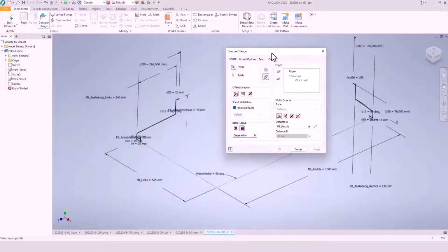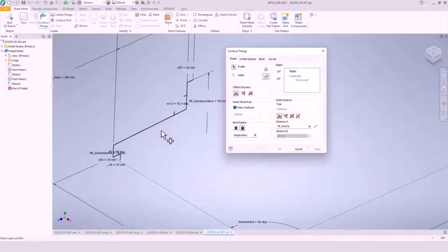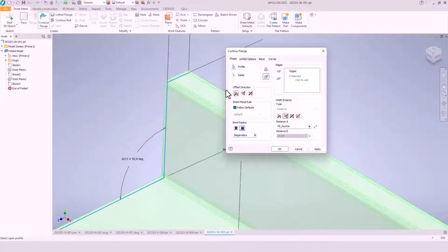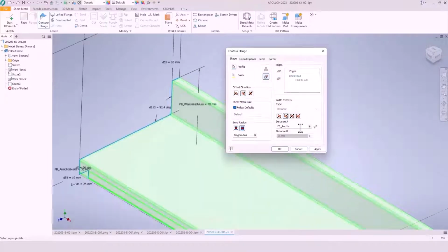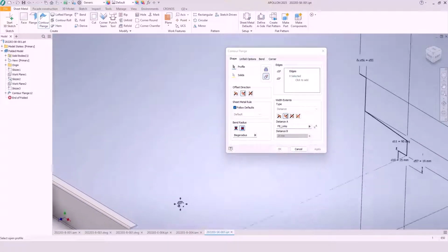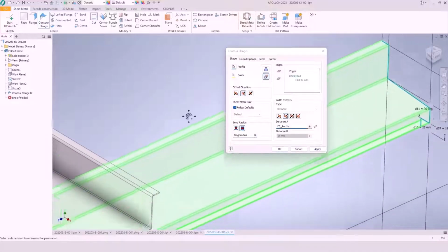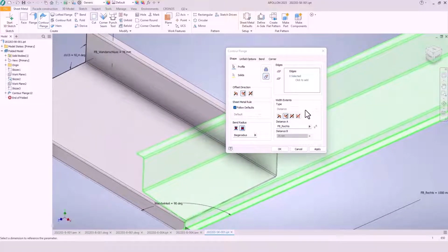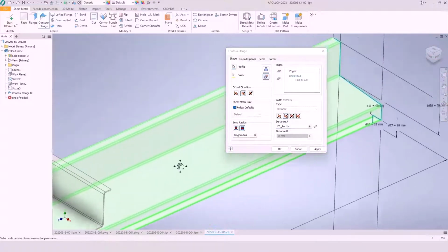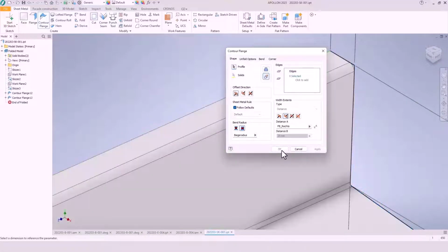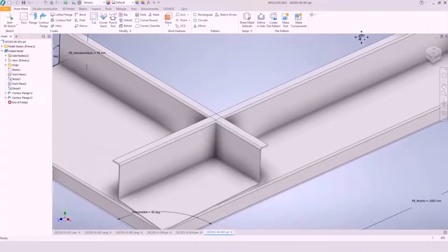With a contour flange, you can simply place a sheet metal cross section over a sketch cross section like here. In this example, our colleague has already stored parameters that we can use to create the different sheets. For the intersection of the edges, we use the corner seam later. So here we have the right side of the windowsill, and we have determined the right side of the sheet metal cross section. Okay.